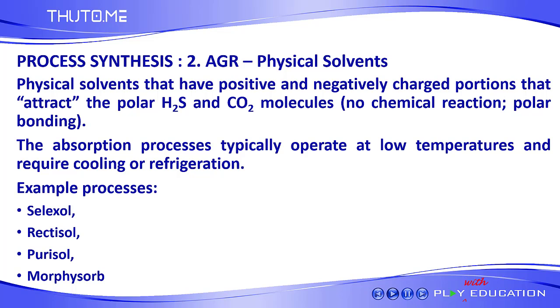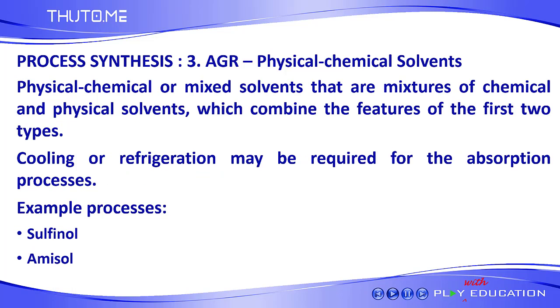The processes usually use solvents such as Selexol, Rectisol, Purisol, and Morphysorb. The names are based on the proprietary solvent that is used to absorb the acid gas.